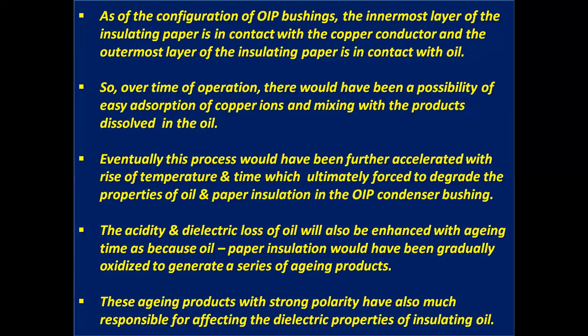In the OIP condenser bushing, the acidity and dielectric loss of oil will also be enhanced with aging time, because oil paper insulation is gradually oxidized to generate a series of aging products. These aging products with strong polarity are also much responsible for affecting the dielectric properties of insulating oil.